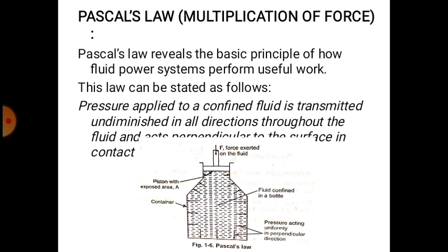Pascal's law. Pascal's law reveals the basic principle of how fluid power systems perform useful work. This law can be stated as follows. Pascal's law states that the pressure applied on a confined fluid is transmitted undiminished in all directions and acts with equal force on equal areas and at right angles to them.